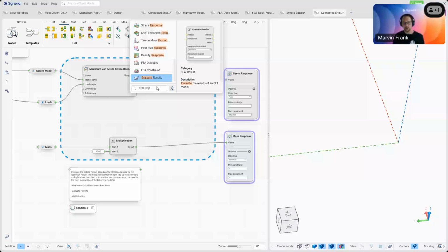Use the standard of 0.3, and now I want to do the automatic reconstruction. Before we do that, we prepare this a bit. For example, sometimes you know that after OptiStruct has run through, there might be little islands of meshes flying around here and there. Of course, they are not part of our main model. In this case, not. The mesh looks good.